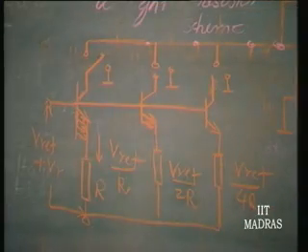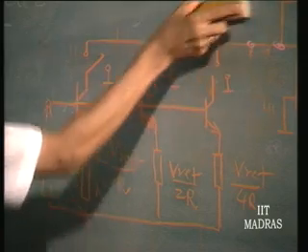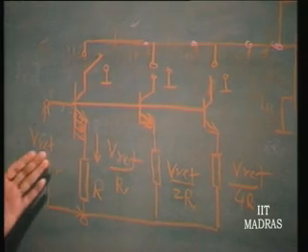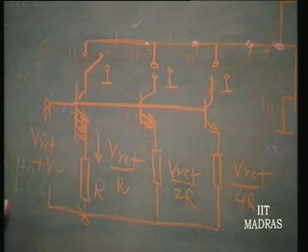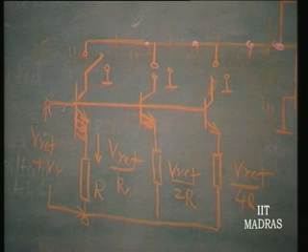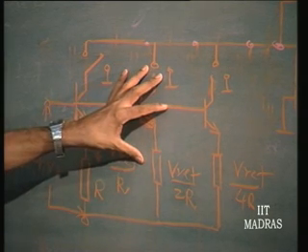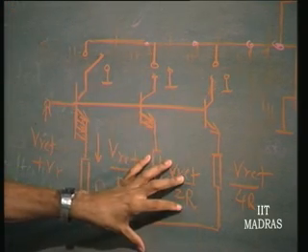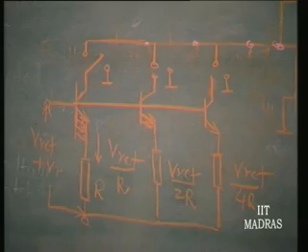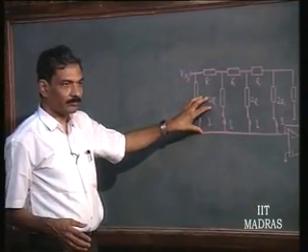Basically, we have seen that it has a weighted resistor scheme and transistor current sources and switches and V reference. Now, this forms the essence of the internal circuitry of a D to A converter. There is a small difference here. There are two schemes of getting the required weights for the summation. One is the weighted resistor scheme, another is called the R to 2R ladder scheme.